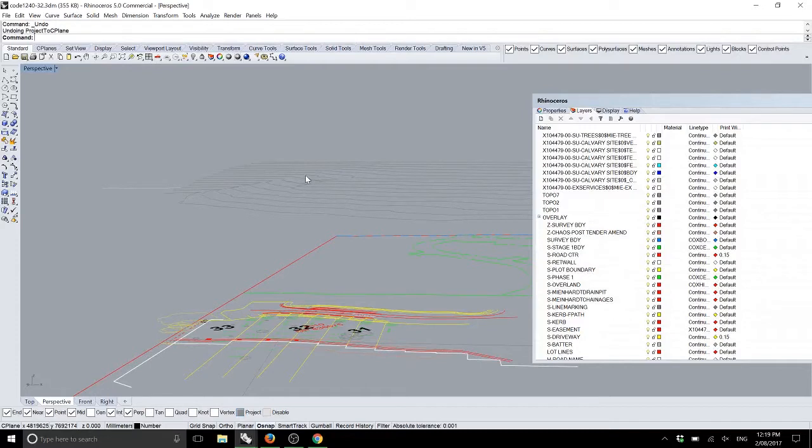So next thing, contours. Everyone familiar with what contours are? Yes? No? Yes? Okay, so contours are what I would consider human readable ways of communicating 3D space. As contours get closer together, you start finding steeper results. As they get further away, it gets shallower. But if you have contours that don't have numbers, ever receive them? Sometimes. But when they send it flat, at least they have numbers. Yeah.